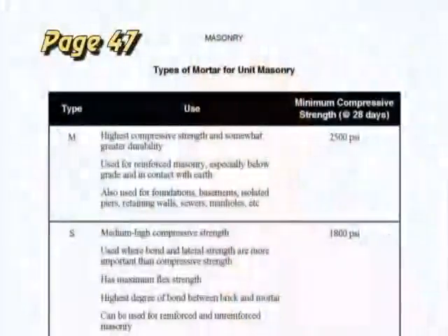So if you lay it up quite wet, or if you've wet it, or if it's come in from the rain, and it's still wet when you lay it up, it's going to be a little bit expanded. And it's going to shrink, and its neighbor is going to shrink, and its neighbor is going to shrink. The end result is that your whole wall will shrink by just a little bit. Hardly anything to measure, but it will create cracks. Cracks you don't want, and cracks that may cause a redo of the job. Read the rest of that, understand what is in those paragraphs,